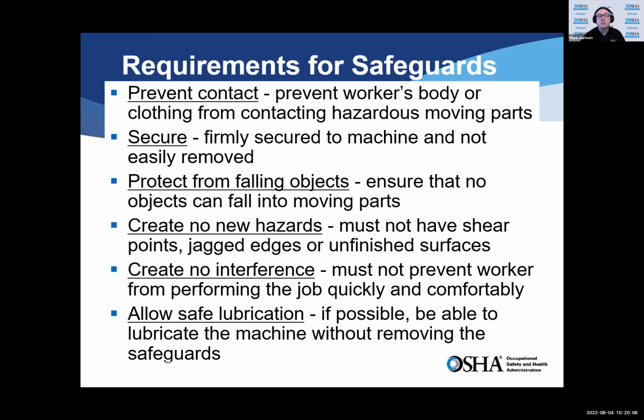Requirements for safeguards, again, bullet point: to prevent contact with workers' body or clothing. I'm glad that it does say the word clothing, because think of the other parts of the body. You've got your hands, I understand, or your feet, but think about long hair, jewelry, things that, when you lean over or you're in close proximity to the machine, can become caught. They need to be protected so that you don't have contact with the machine.